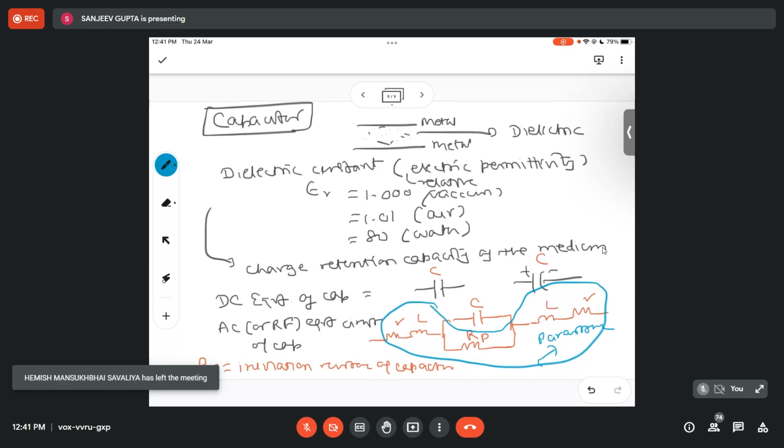And when I solder it, you will find additional capacitance, say a nominal value like 0.3 pF in the previous case. Your capacitor is also no more a simple capacitor.